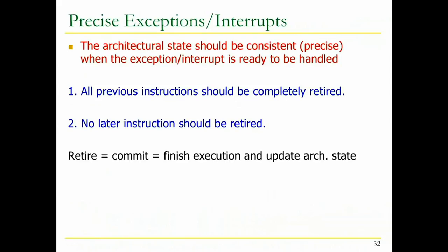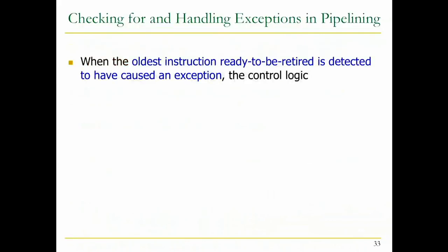So retire is also used as commit. You'll see this terminology. It means finishing execution and updating the architectural state. Some people also call it graduate. I guess it's similar to graduating from college or somewhere, but I don't like that term as much, and it's not as commonly used also.